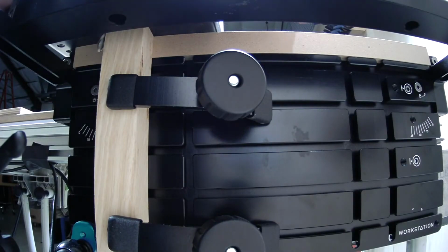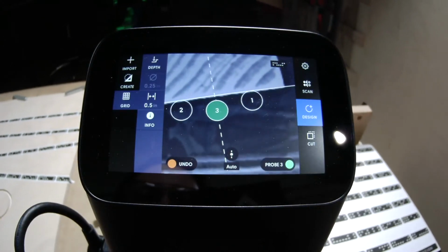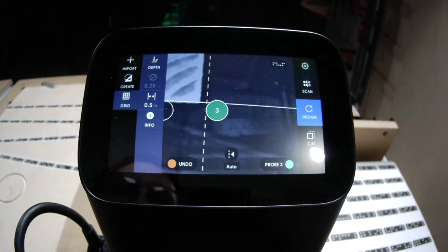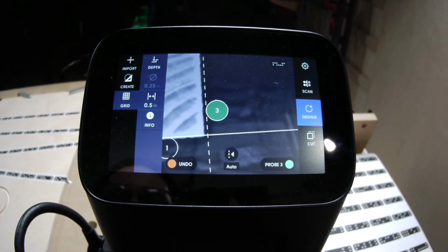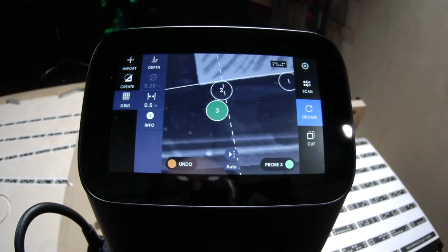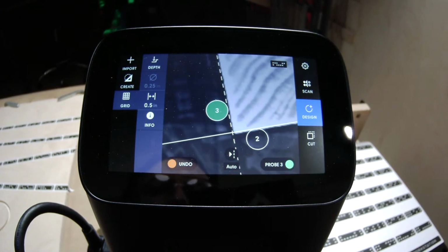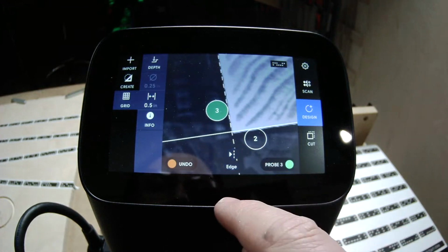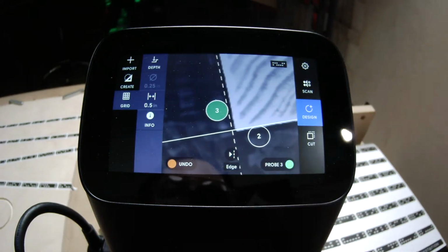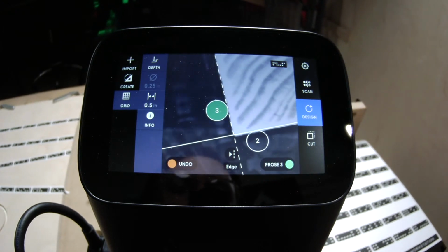Before I do that, though, you can see if I wanted to do something in the middle, I could totally do that. The line actually switches to the middle, or to probe on the opposite side. It's okay to probe on any point, whether it's somewhere in the middle or on the left-hand side or right-hand side of stock. That was a change made with all of these updates to the grid tool. So if you didn't know that, now you do, and you can swap here as well if auto mode isn't working for you. But auto mode's pretty great. Thanks, Sean, for that, and Sam.